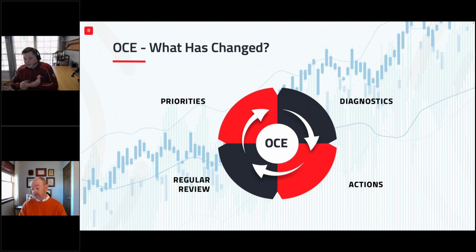It helps you do diagnostics, right? If a loop that has always run at 100% OCE is suddenly down at 0 or 20 or something like that, hey, wait a minute, something's wrong here, something has changed. It draws your attention right to that. Like you said, the prioritization is really critical. You have 2,000 loops in your plant. You simply don't have time to look at all 2,000 loops every day, let alone take any action to improve them. That's right. Being able to prioritize, to find those things that change.